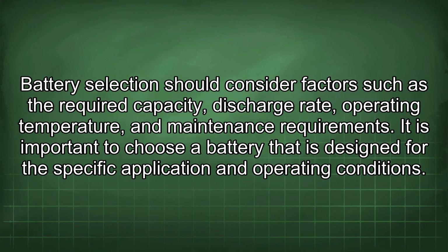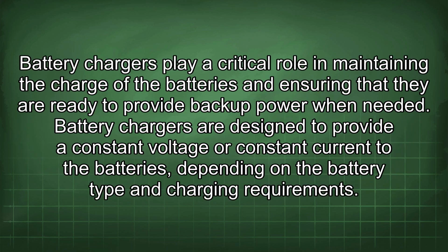Battery selection should consider factors such as the required capacity, discharge rate, operating temperature, and maintenance requirements. It is important to choose a battery that is designed for the specific application and operating conditions. Battery chargers play a critical role in maintaining the charge of the batteries and ensuring that they are ready to provide backup power when needed.